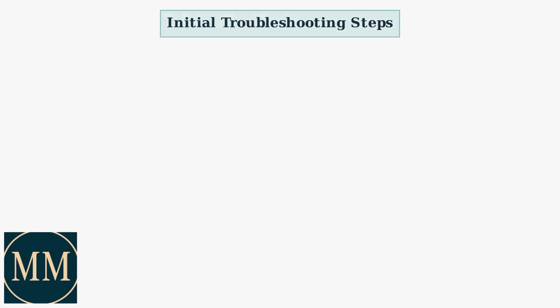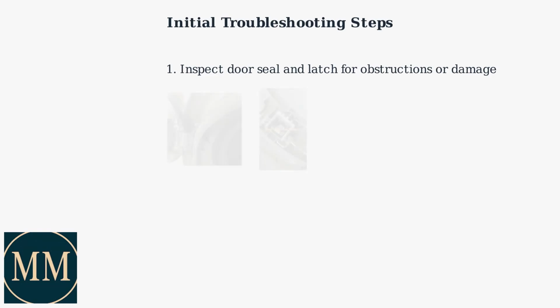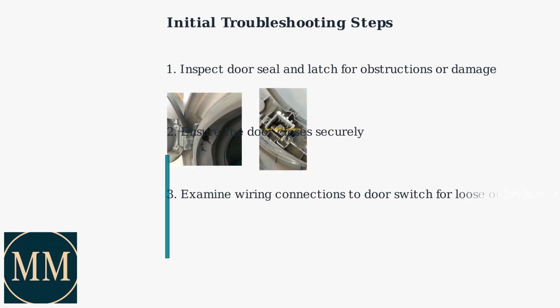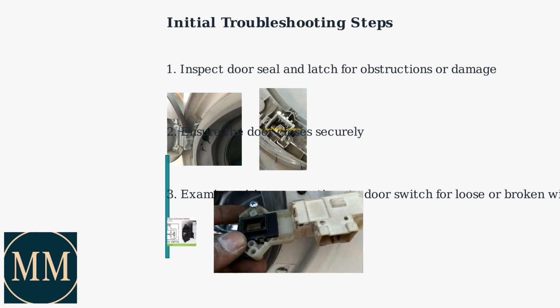Begin by inspecting the door seal and latch for any obstructions or damage. Ensure the door closes securely. Next, examine the wiring connections to the door switch for any loose or broken wires.